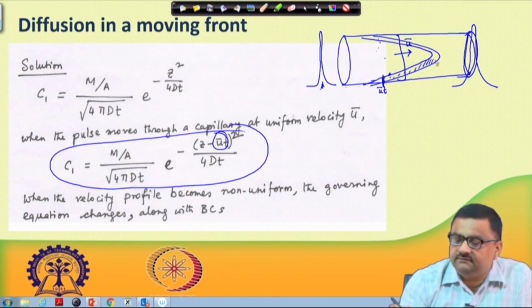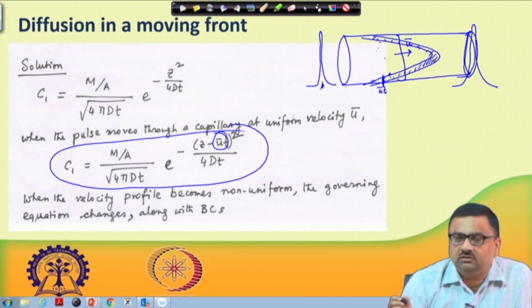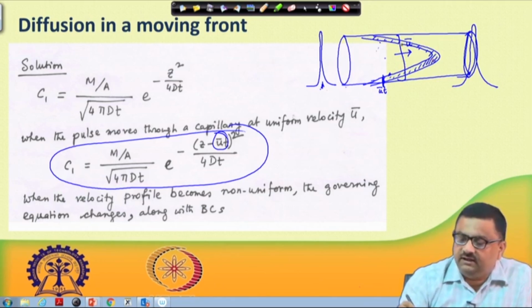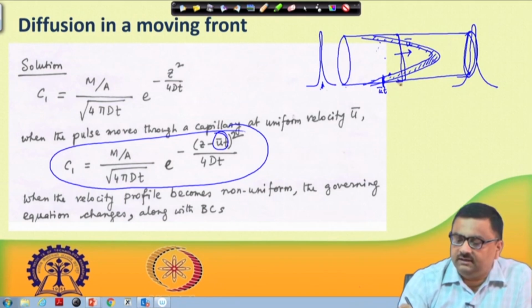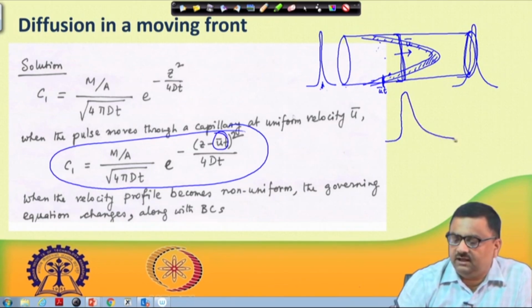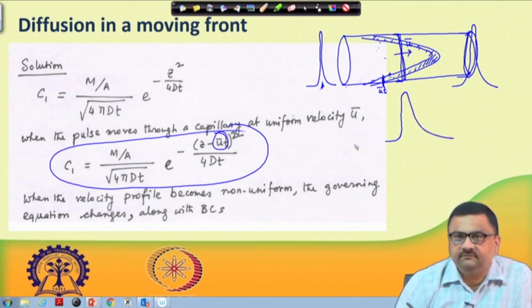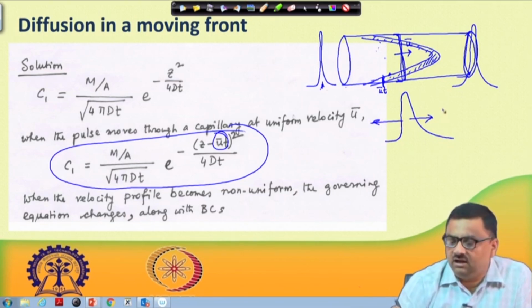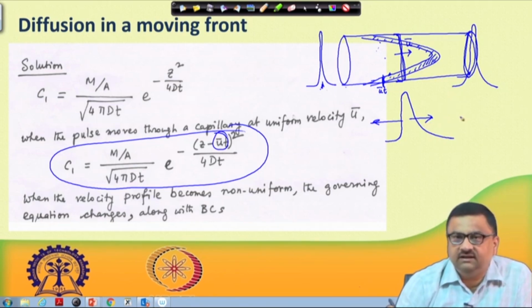So, this is where we have higher concentration, and so now earlier what we were thinking, that if there is a single straight front like this, so as if this was the center of the pulse and this is how it is diffusing. So, it can diffuse to this direction and this direction, and then we had a governing equation by taking a differential dz, and then volume, in minus out accumulation and Fick's second law, and all those things we had done already.